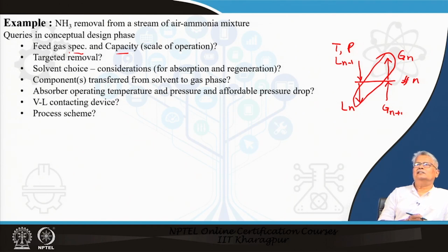One reason these two are quite common, and a number of absorption processes are carried out in packed bed, is that you really do not require too many towers, too many ideal stages for the separation. And it is more so because you would prefer to choose a solvent which has high solubility for the component that you have to remove.